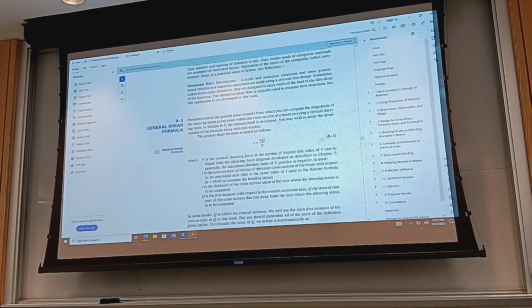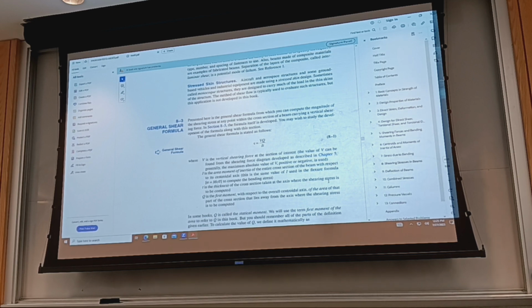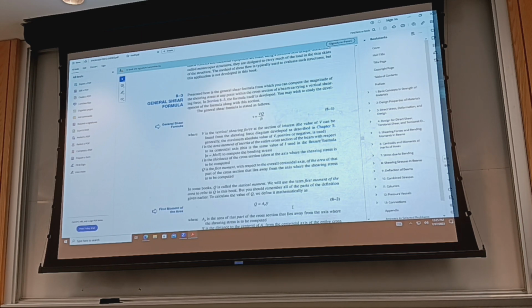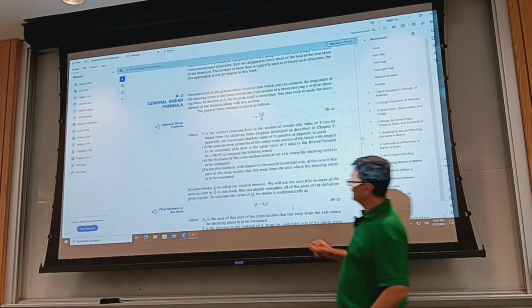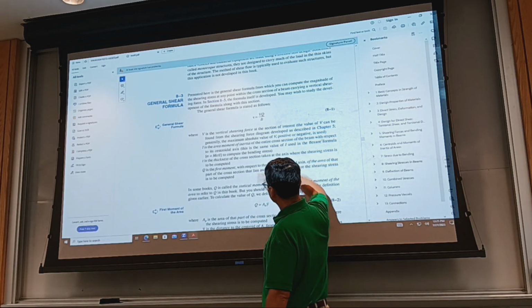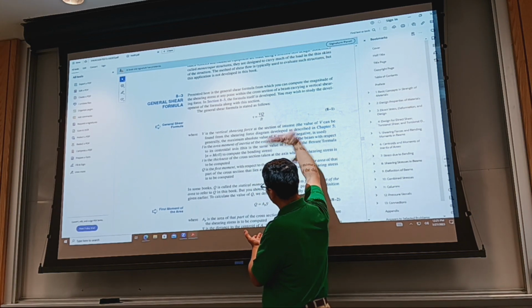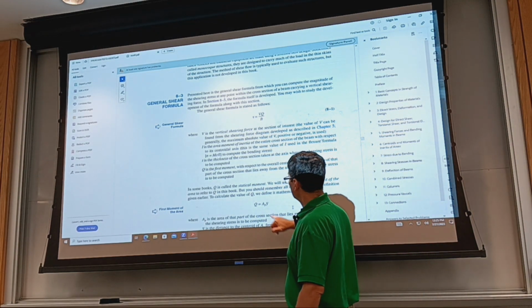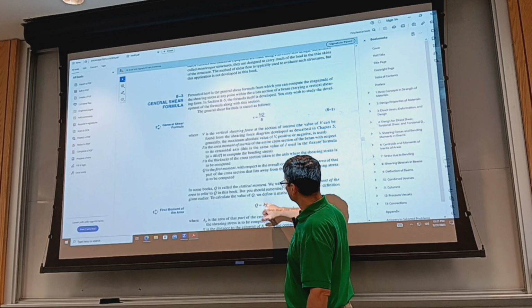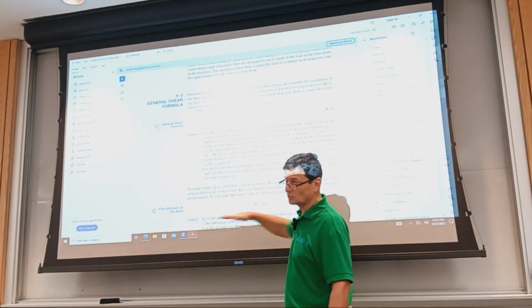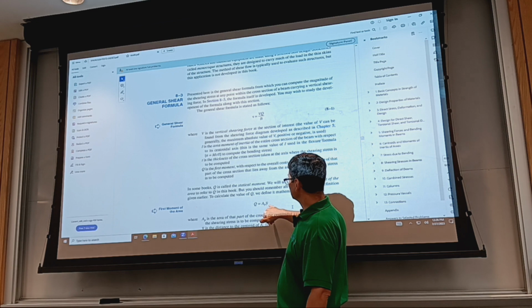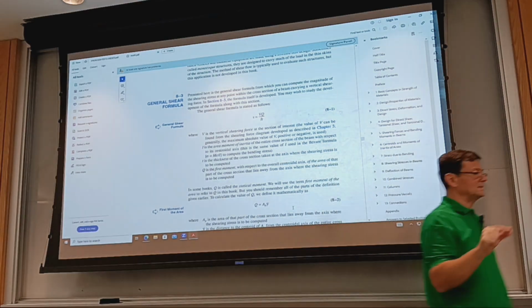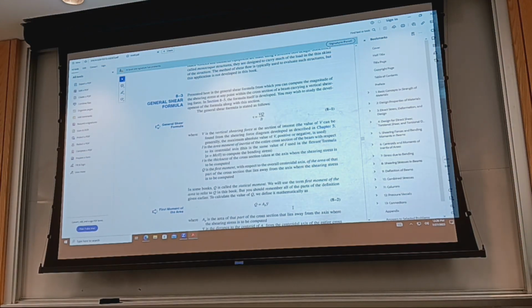This is done in some sample problems where you can see that stress distribution. Again, Q is the first moment of area, and how do you calculate it? It's the product of the area of the beam cross section above, could be below, they are equal, the part of the beam above the horizontal plane where I'm doing the analysis, times the distance from the centroid of the assembly to the centroid of that delimited portion of the beam.